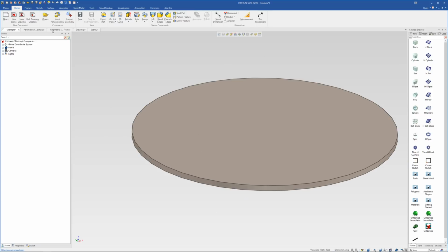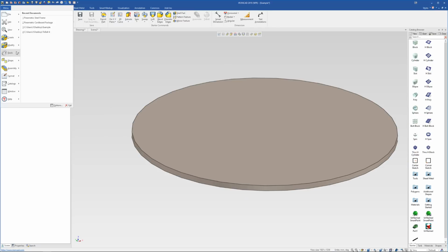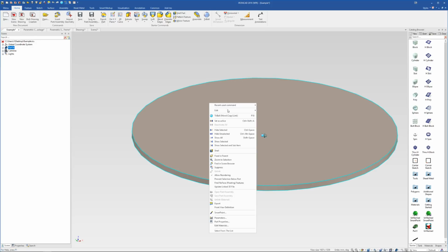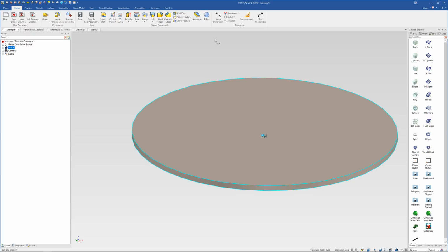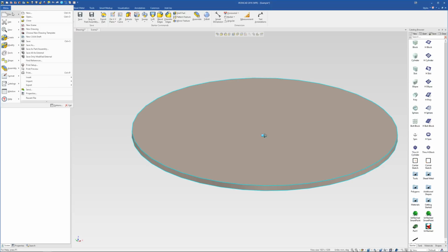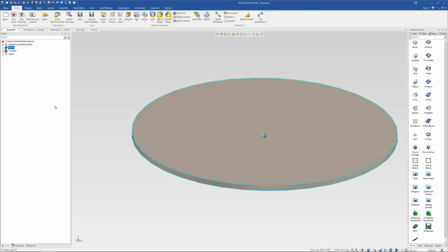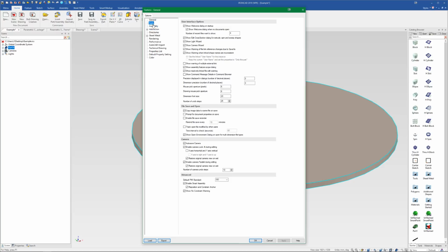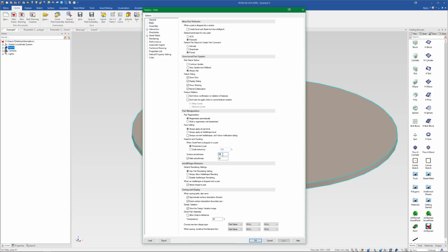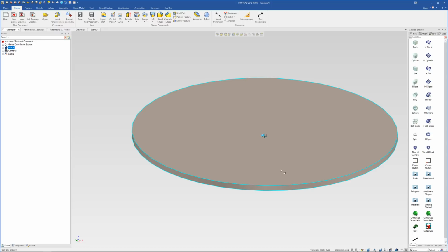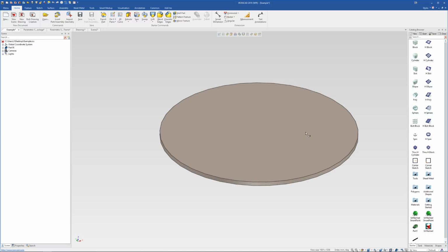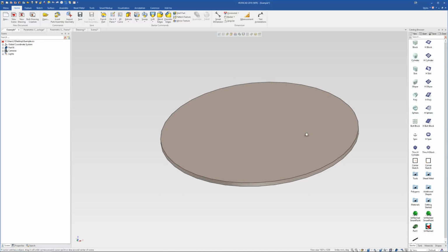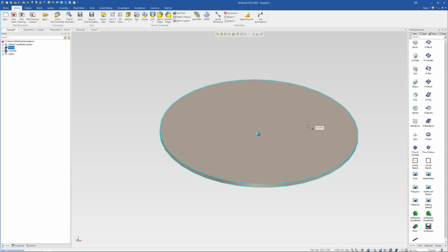So what you can do, especially if you have a computer that is powerful enough, and you can just test whether it is, is change this through that area I went to, which is the part properties rendering on an individual part basis. Or you can go into the options, then go to parts and change the default. See my default is 60, just double the normal size. Obviously that's going to use double the graphics power, but if your graphics card's powerful enough, there's no problem. I'm using a laptop with only a 4GB graphics card at the moment, so 60 is no problem.